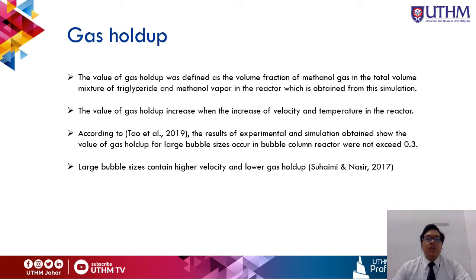For the gas holdup, the value of gas holdup was defined as the volume fraction of methanol gas in the total volume of the mixture from the simulation, and the value of gas holdup increased with increasing velocity and temperature in the reactor. According to Tao et al., the results of the experiment and the simulation show that the value of the gas holdup for the largest bubble size occurring in the bubble column reactor will not exceed 0.3, and a large bubble size contains higher velocity and the lowest gas holdup, based on Suhaimi and Nasir.